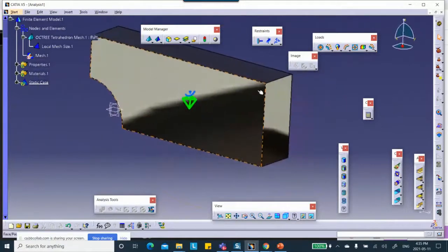Now, if we were applying force here, 2,000 pounds, don't use 2,000 pounds, divide it by 4, right? Because the 2,000 pounds was applied on this big rectangle here, which we cut into 1/4 of it. So if you apply force, do 500 pounds.